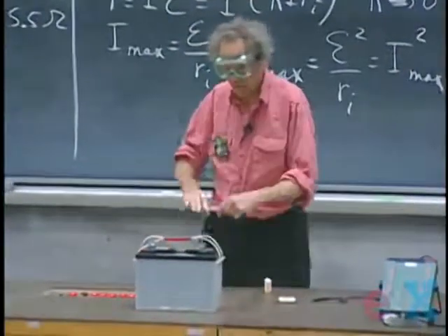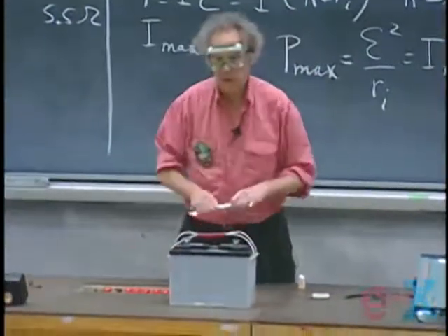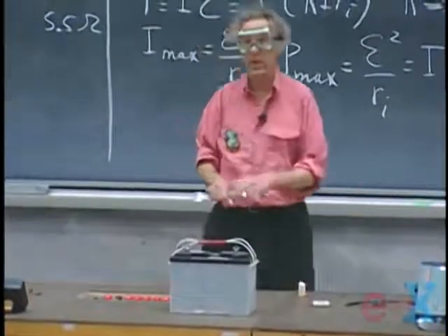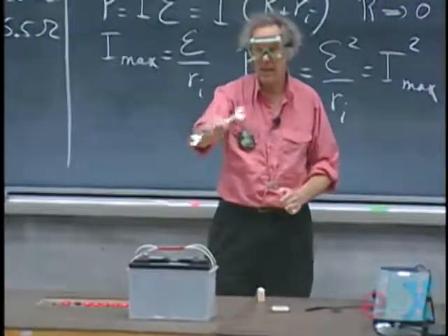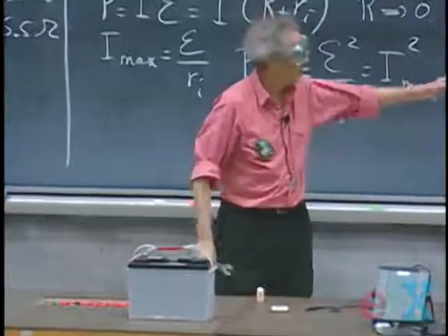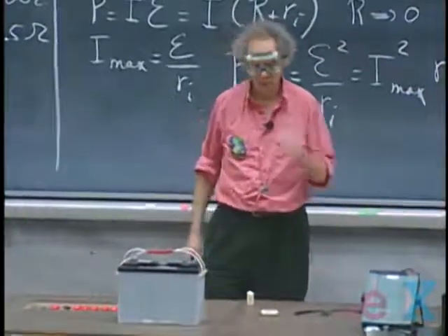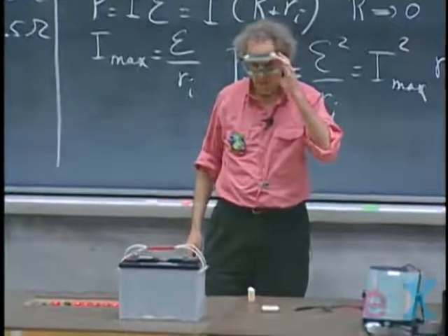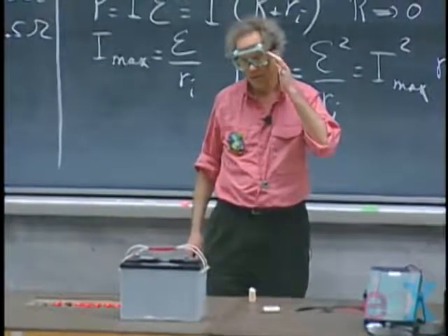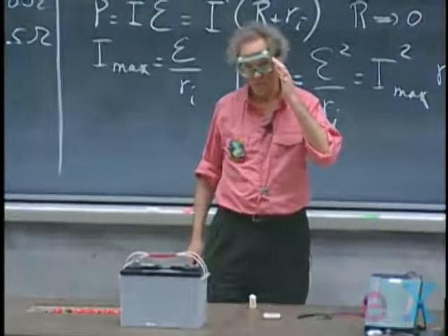I will be very careful not to hold on to this wrench too long, because it can weld onto it and stay there. The current is so high, it can go up to 600 amperes, that it can weld onto it, and then you can't get it off anymore. In case that happens, I will walk out of here, and I advise you to do the same.